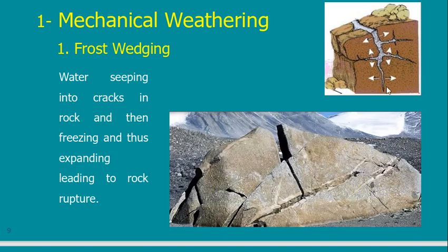But what is the effect here on this? Once this amount of water freezes, it wants to expand. Once it expands, it pushes the side. So if I have a small crack, next year it will be bigger. And the following year it will be full of more water, and the more water wants to expand, so it pushes again, and so on. Each year, freezing, thawing. So what will happen in the end? The crack is going to increase.